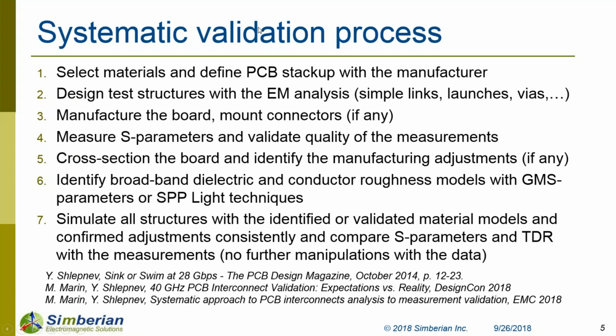These can be validated in Simbeor. After we are satisfied with the measurements, we cross-section the board and identify the manufacturing adjustments, to see whether the manufacturer's expectations for the trace width actually correspond to reality.